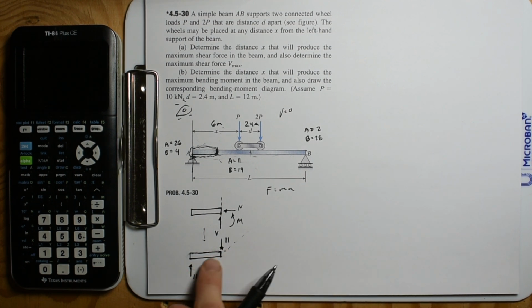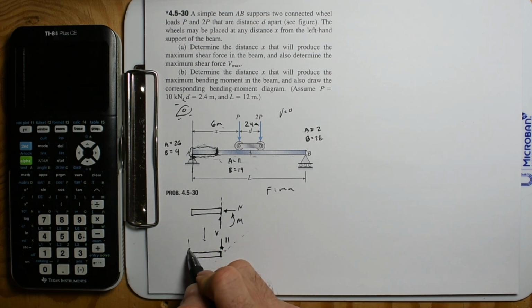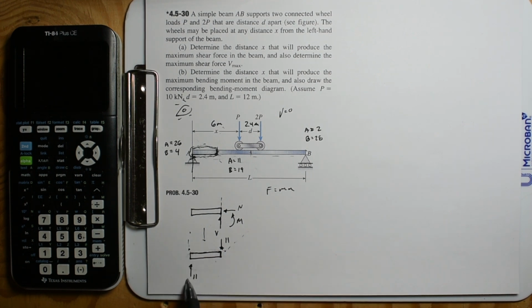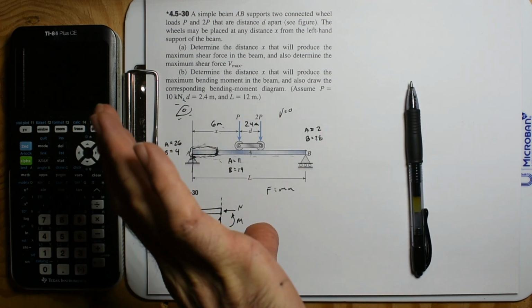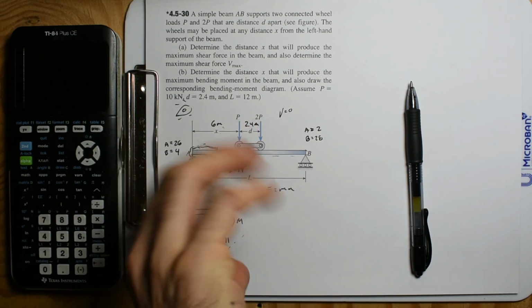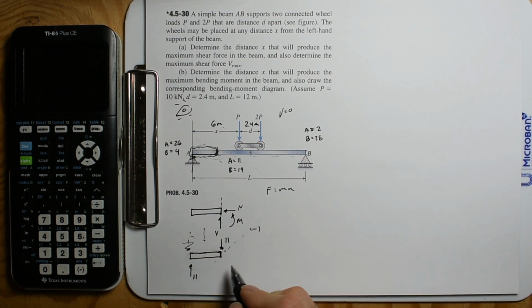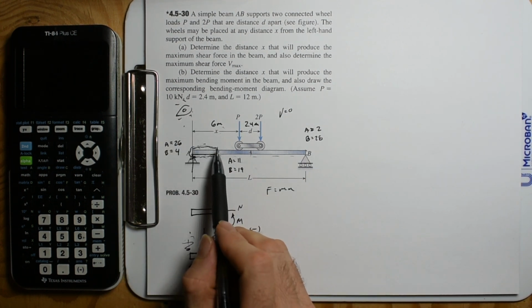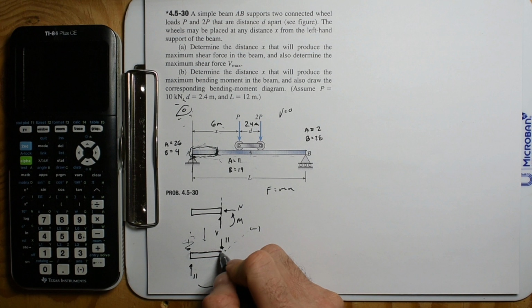So now the forces are balanced, but this 11 kilonewtons isn't right here. If it was right there, then it would be nice and balanced. But because it's over here, this is going to cause the thing to spin. Using the right-hand rule, this force is going to cause it to spin that way. This force is going to also cause it to spin that way. So it's going to cause a negative moment. But we know back on Earth, this thing isn't spinning. And so we must have a positive moment that prevents it from spinning.